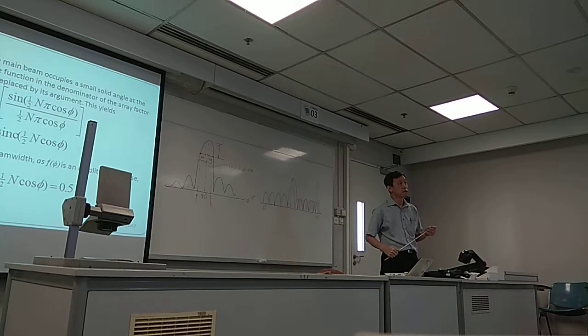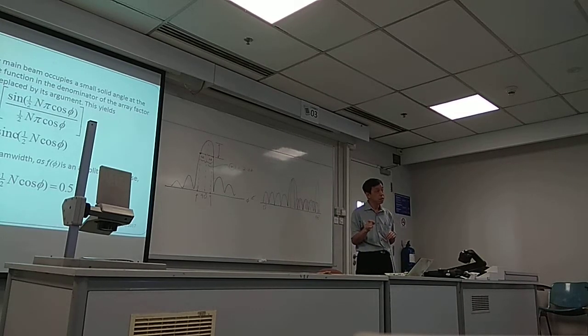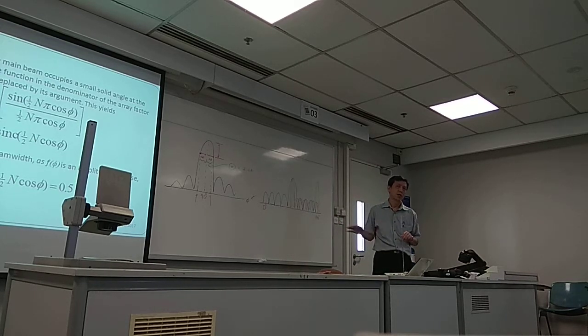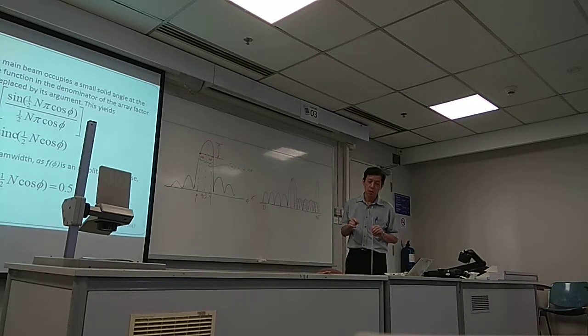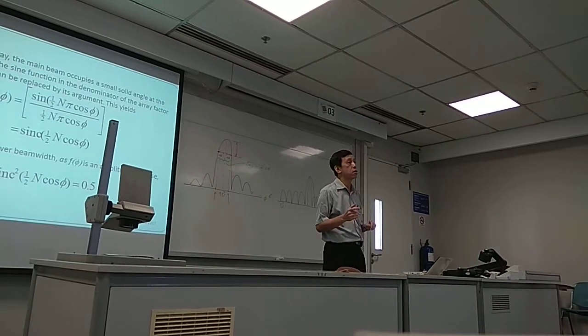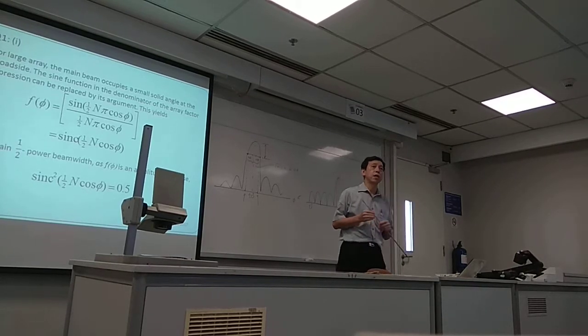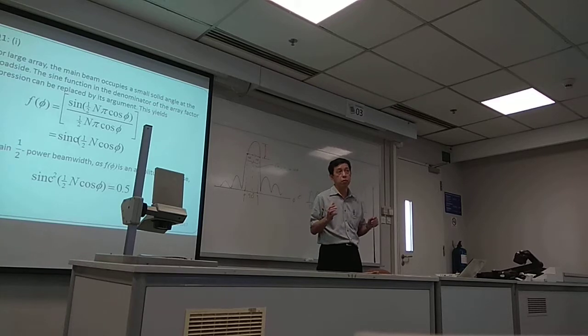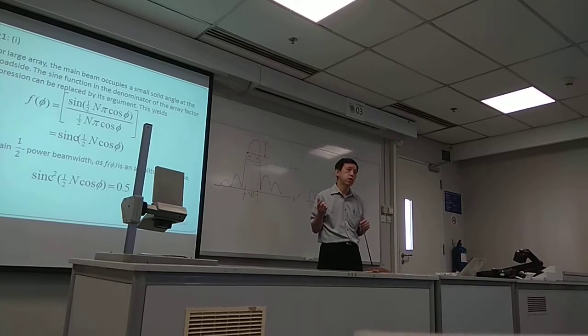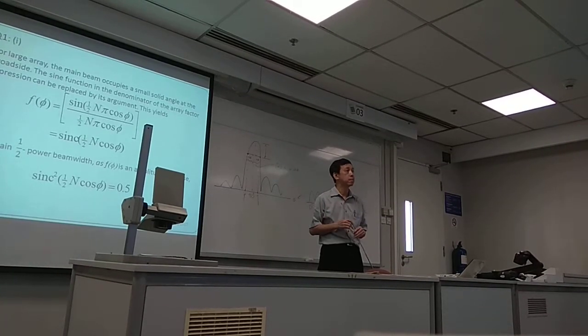linear array with so-called spatial aliasing being tolerated. So you can actually tolerate to a certain extent the so-called aliasing problem in the spatial domain. Now, it is a very specific topic, but it is possible in real application. You can actually violate the sampling theorem to a certain extent. So, though that can be done, a lot of time we just simply ignore it, and we just simply assume that the inter-element spacing is always half wavelength, though this assumption is not a necessity.